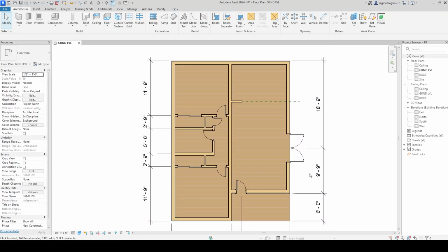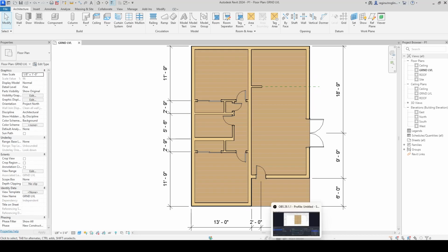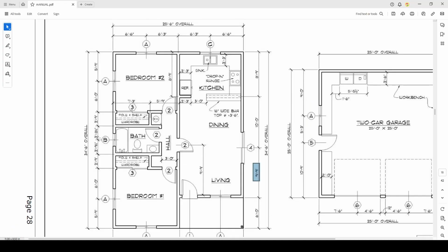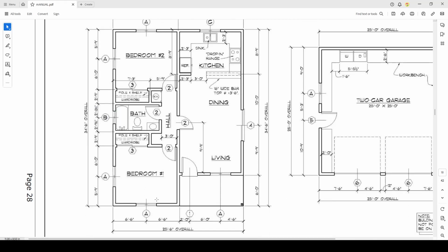So that looks like all of the doors. So now that all of the doors are done, we can move on to the windows. And again, window symbols are always circles, as well as on plan, the actual window itself, if it's a slider or a casement, each of those has a very distinct symbol within the wall on the floor plan. It does take time to get used to those different symbols, but I will do a separate video on what each of those looks like, as well as what each of the door symbols looks like on plan.